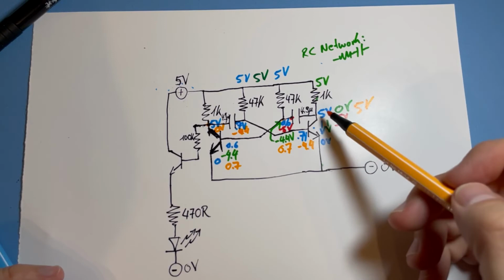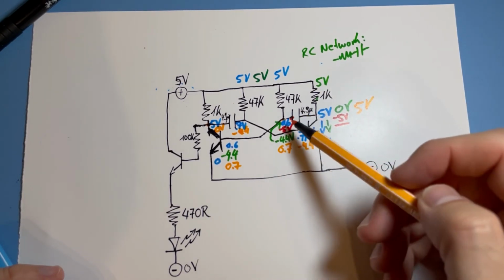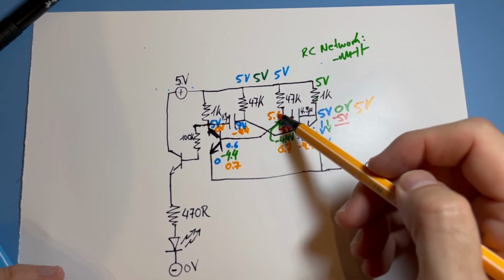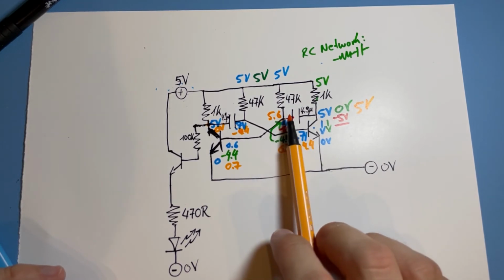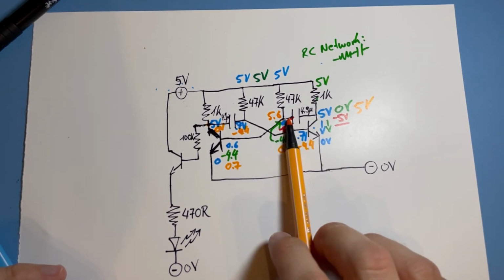You have again then 5 volts on the right side. That's an upwards of 5 volt, and then for a short amount of time 5.6 volts to the left here. So actually a small correction. The capacitor tries to go up to 5.6 on the left, but when it rises and hits 0.7, it doesn't go above 0.7 much, maybe 0.701 or something.